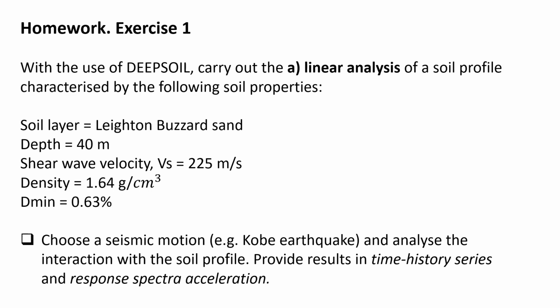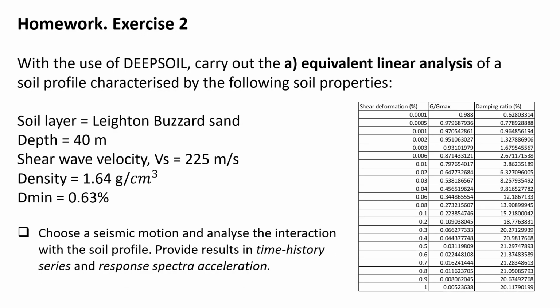As part of the homework, what I'm asking you to do in this case with exercise 1 is that with the use of DEEPSOIL, carry out the linear analysis of a soil profile characterized by the following soil properties. These are real data based on some experimental investigation that I conducted a couple of years ago. The soil layer is mainly Leighton Buzzard sand with a depth of 40 meters between the soil surface and the moment when we reach the bedrock.